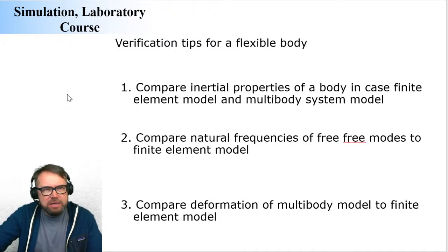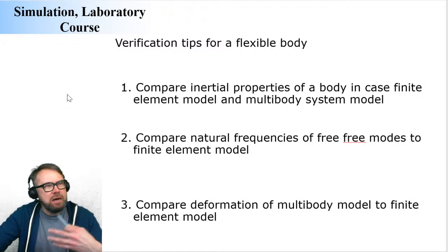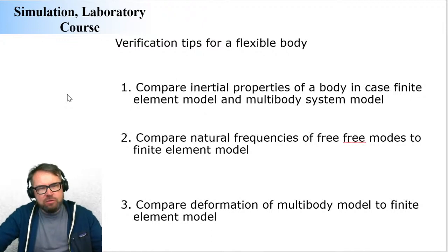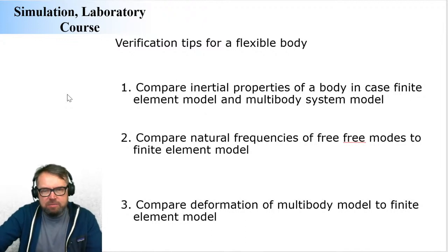And if there's any change, that's when you need to figure out where the change is actually coming from. You can also compare their natural frequencies using these free modes. You can conduct an eigenvalue analysis in your finite element model, and then you can compare that against the modes you're using in your multi-body system dynamics models. And visually, you can compare how the deformation looks. So those are the three verification tips.